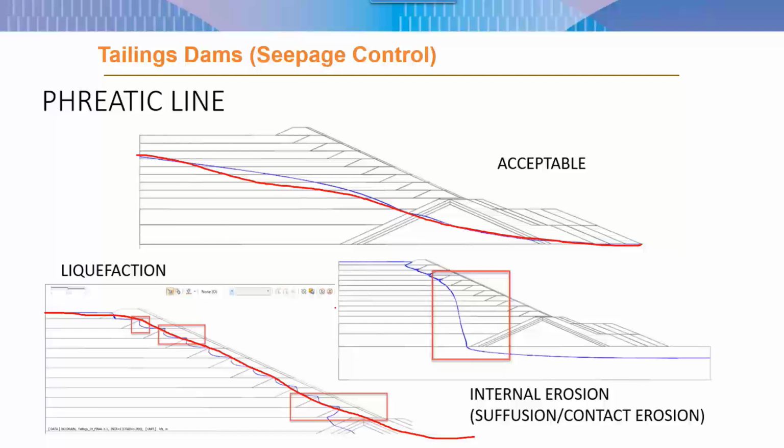Due to that region, the flow is quite high and the dams are made of earthen materials, which essentially means that high pore pressure along with excessive seepage as a result might also cause liquefaction of the core material.